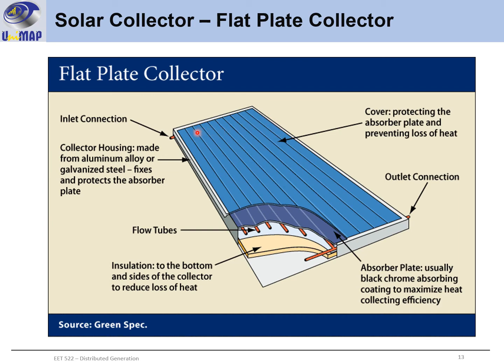This figure shows the main components of the flat plate collector. On top of it we have the cover plate, this area here. Usually this is made of transparent material, as well as the glazing material. And then just below that we have the absorber plate. So this is the part where the heat from the sun is absorbed, and the energy will be used to heat the water or the liquid inside the tube. The tube comes from here, the inlet connection, and will go out from here.